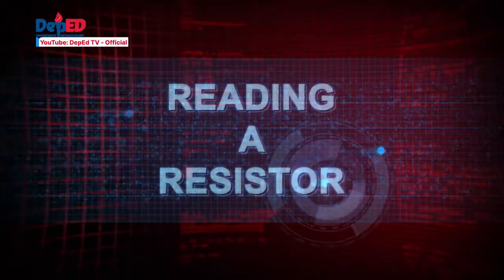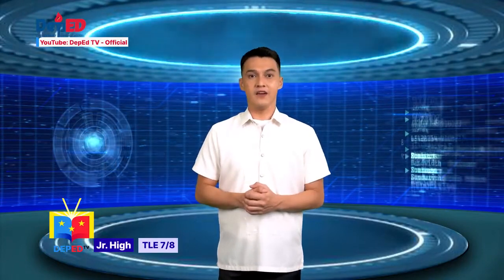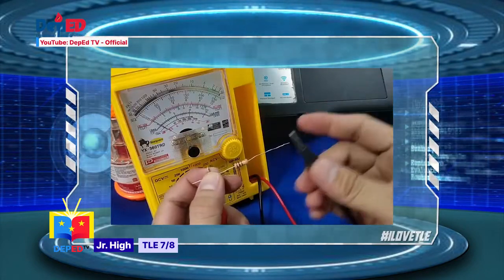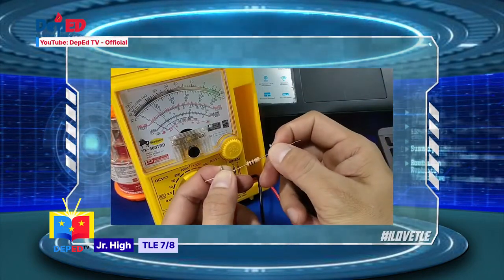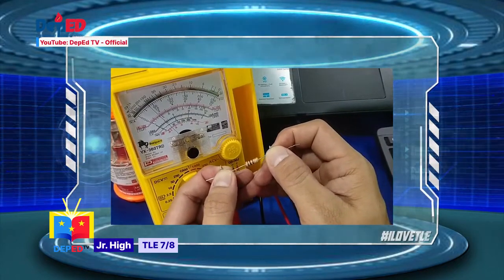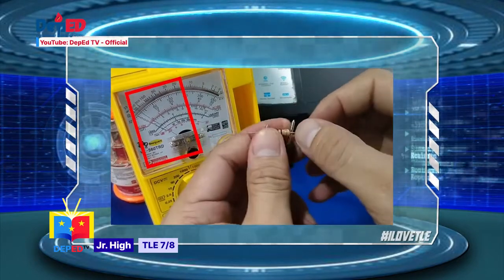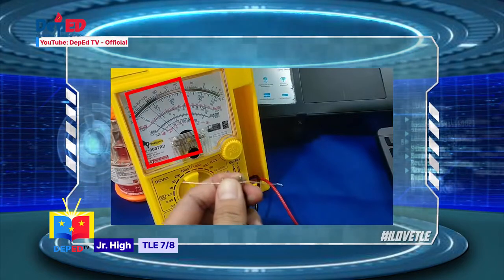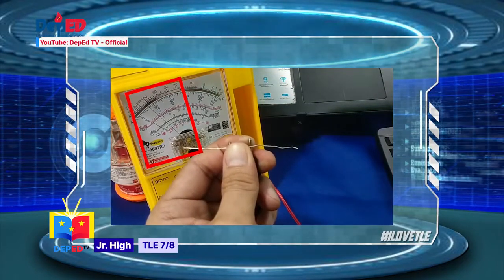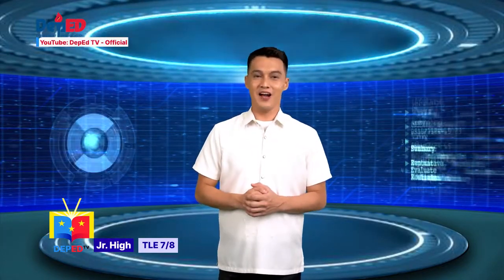Since we know the value of the resistor, let's check if our manual reading is correct. Attach the test probes at both ends of the resistor. There is no polarity involved, so you may connect the probes wherever you need to connect them. Observe that the ohmmeter reading is at 100 ohms with a 5% plus or minus value. Therefore, your manual calculation is correct. Congratulations! You just have learned how to check a working resistor.